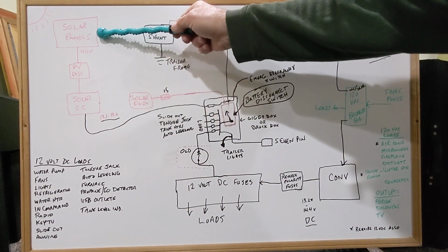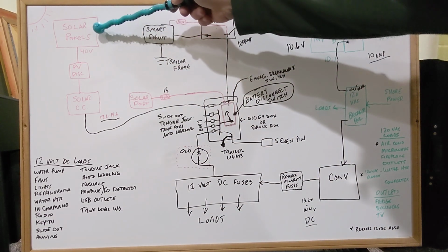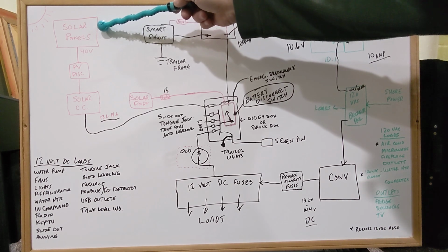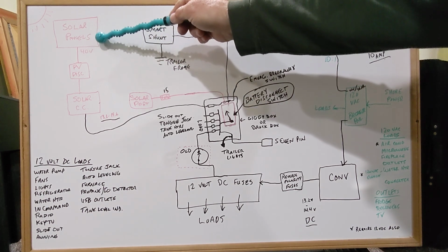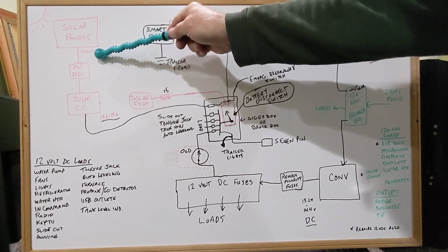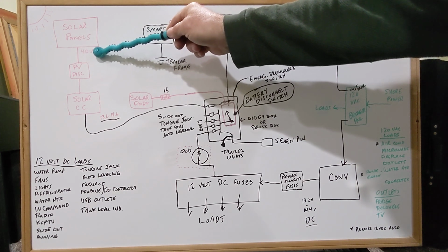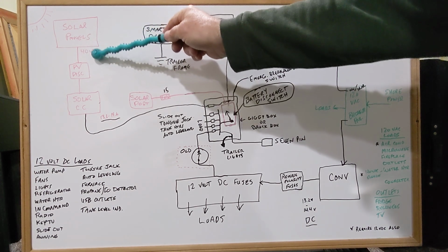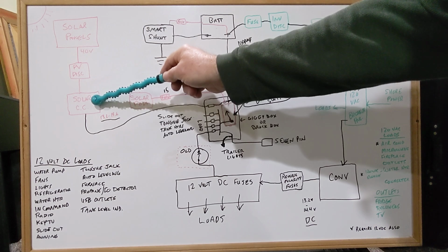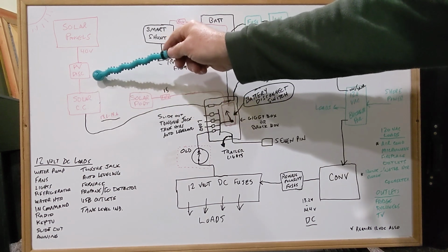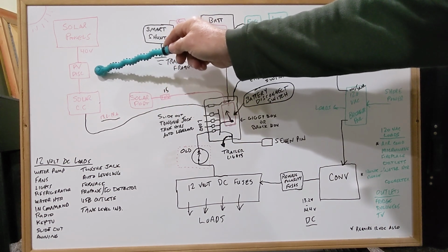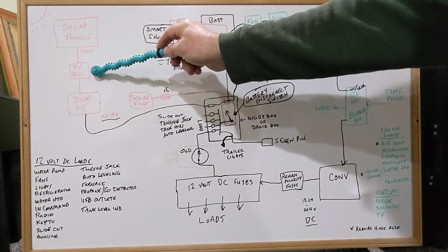And then if you've got your solar panels on the roof, you've got 200 or 400 watts or whatever, and they're generating DC power. The newer panels come out around 40 volts DC, and it comes down into your solar charge controller. Now in the newer trailers, 2023 and later, they started installing this PV disconnect switch.